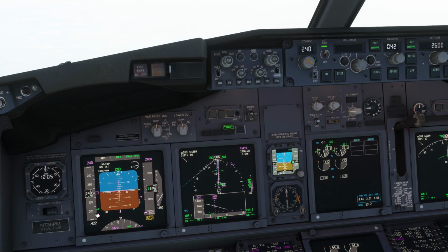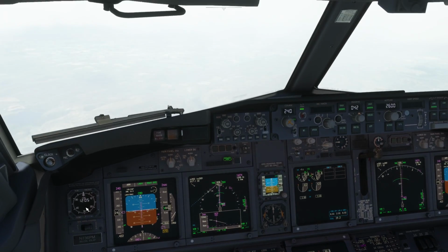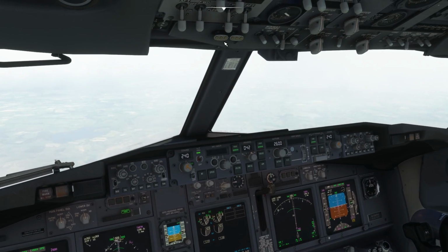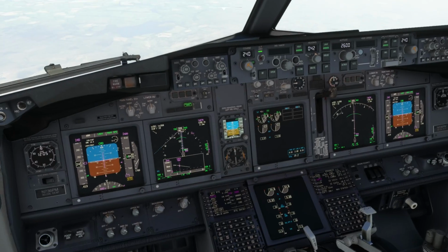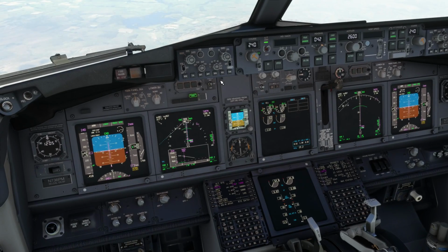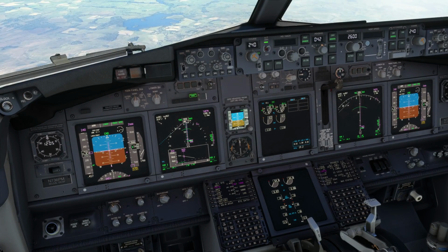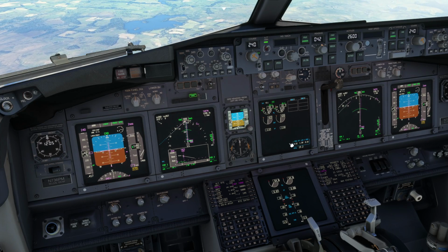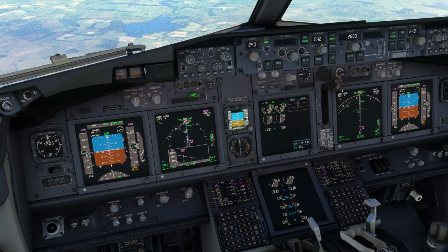So as we start decelerating, we need to control the flaps. The airplane won't do that for us. And we can get the gear down and everything else in good time. So we're below 10,000 feet now, so we'll get the landing lights on. We're going to be landing incredibly heavy. We just went with the stock fuel load that the simulator gives us.